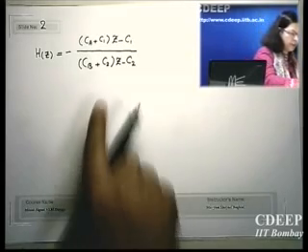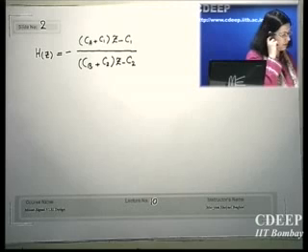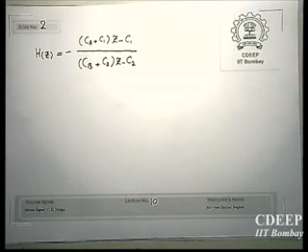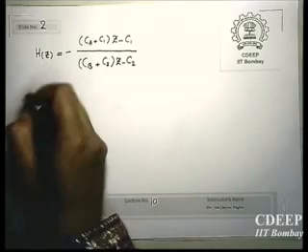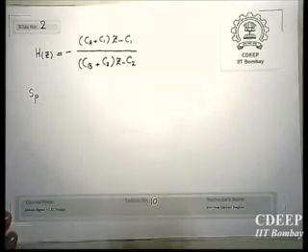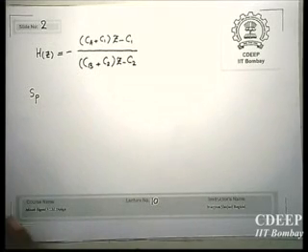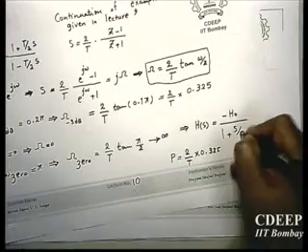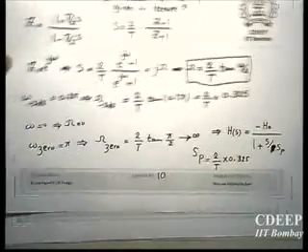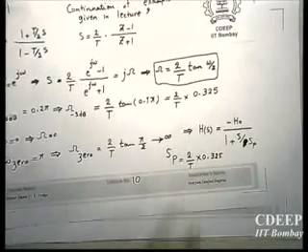Okay. So now we have this transfer function and now we know the characteristics. We just want to derive the values of these four capacitors. So I know my pole, now I write it in this way, right? I write SP. The reason I write SP is because I want to discriminate between the Z and S domains. So here also I could have written SP. Okay, so this is in the S domain.